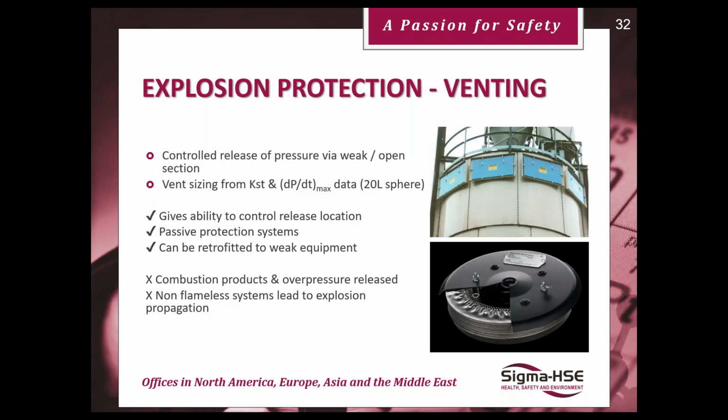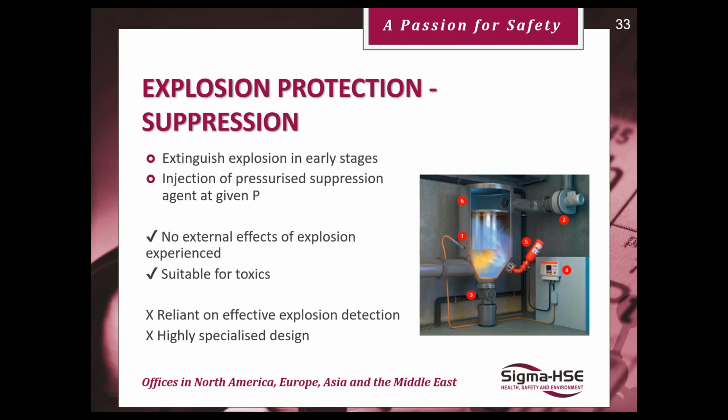Venting is very typical; we can use venting to keep us safe, so the impacts of the fire and explosion leave the vessel and we're not generating missiles from the processing equipment. But of course, the flame and pressure that comes out of the vent needs to go to a safe location. And suppression: put it out as quickly as we can find it. Okay, so that's the standard approach.